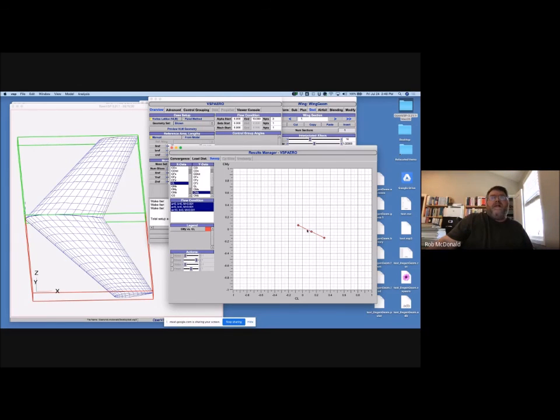And what that's telling me, right, is that with my 0 degree deflection, this is my trim point. But again, if you can imagine, if I then deflect the control surfaces, I've got a parallel line over here. It's going to intersect this vertical axis, this 0 line, at another point, say over here. And so that other control surface point is going to have a different trim point, right? 0 moment is going to happen at a different CL. And so I control what CL I'm flying at by controlling that control surface, which I'm doing by dialing in trim. I know it's like a fire hose right now.